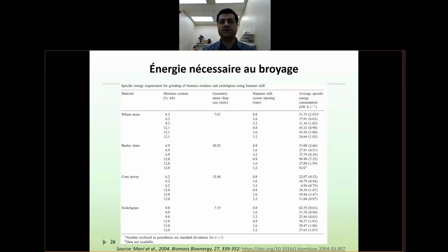So the solid biomass after drying is recovered at the exit of the dip leg of the cyclone, and at the outlet of the cyclone the steam is out. So when we say flash, it's about the fast contact between biomass and hot air. Usually it is air, the flue gas. And when we say flash, it means that the flow rate here is really, really high. So in a matter of seconds, the drying happens.